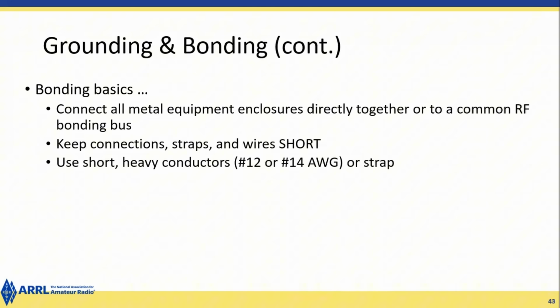Steady hum? Transmitter on the air, on off? It will be just distorted speech, that's the big one. What sound is heard from an audio device experiencing RF interference from a CW transmitter? Again, some clicking sounds, on-off clicking sounds.